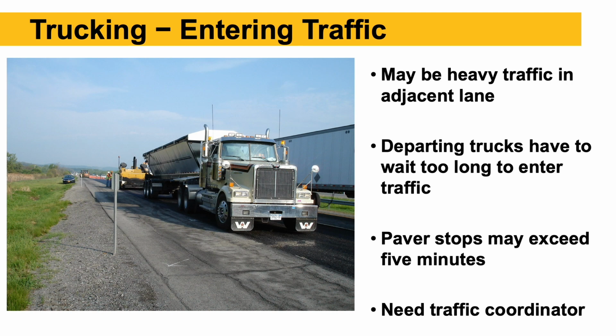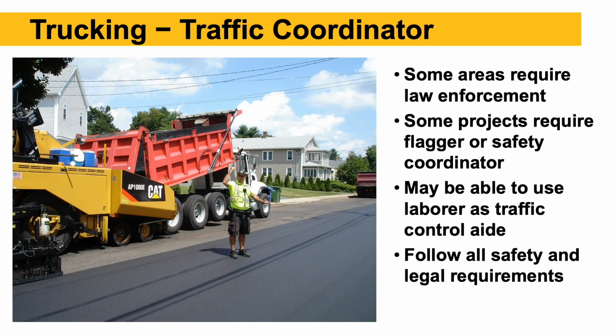Trucks entering traffic, so again on mixed delivery, some areas traffic's really bad. We could be waiting a long time with that paver stopped just to get trucks in and out of the job site. So some jobs, it's nice to have a traffic coordinator. Some jobs it's actually required, as you'll see in this picture. This guy is here stopping traffic so he can let the trucks in and out in front of the paver so that they can try and keep that paver moving.